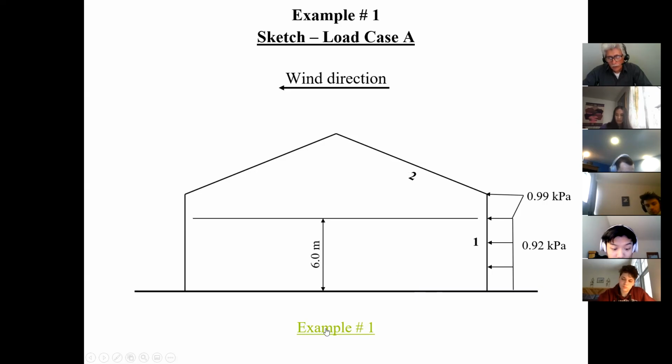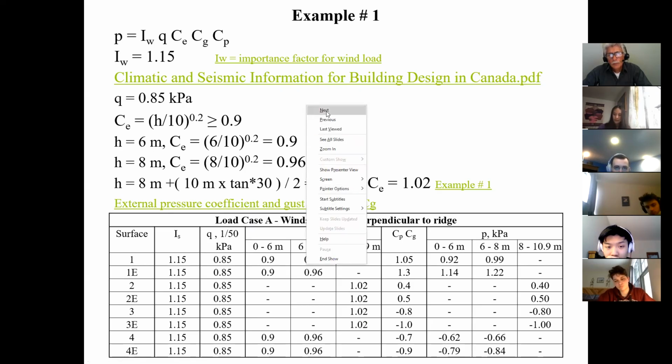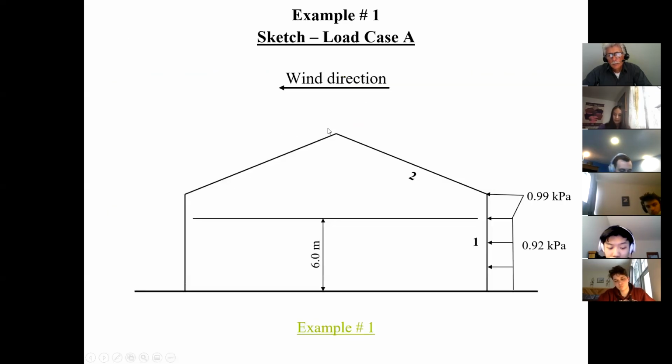Okay, so if I go to surface number 2, now surface number 2, it only has one value. Okay, now surface number 2 is positive. So that's first thing I look up is positive. Okay, so surface number 2 is positive. So therefore, I show the arrows pointing towards the surface, and then it's got a value of 0.9 kPa. Okay, and that's how I make sure I'm okay.